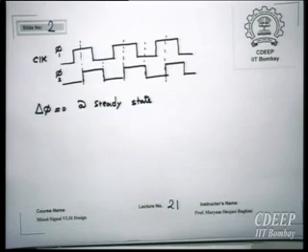Now suppose this VCO frequency is given to some delay components which generate some delay. What is delay? Essentially delay means phase shift. So if they generate some phase shifts, then after a number of stages, at the input of the PLL the total phase is 0. Therefore, the total phase will be divided by the number of elements, and you will get n number of phases. So the circuit will be something like that.